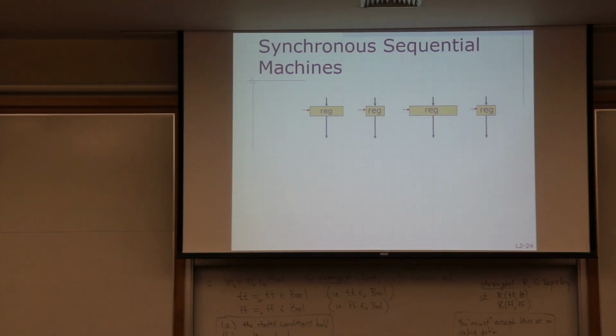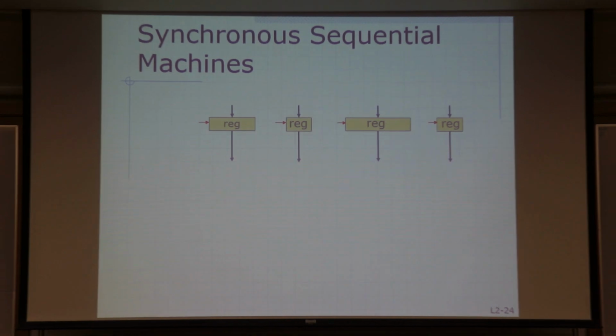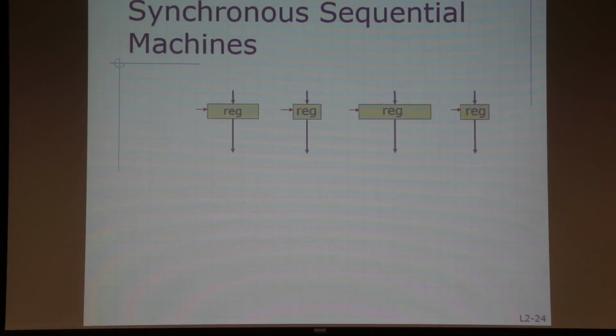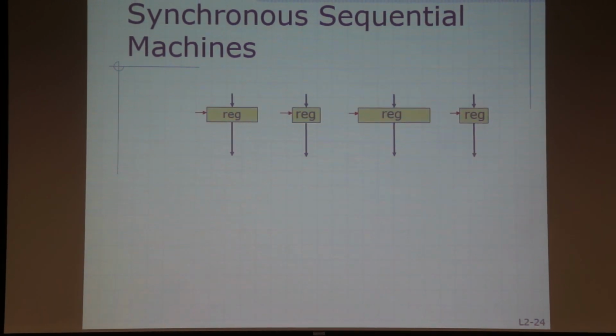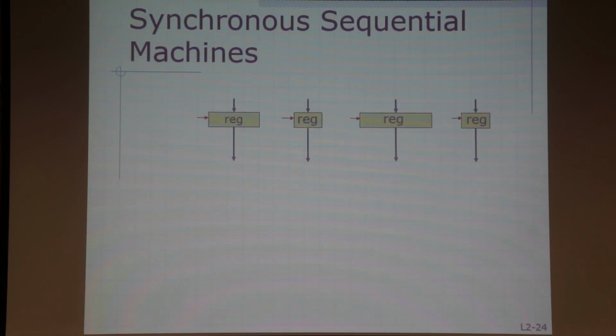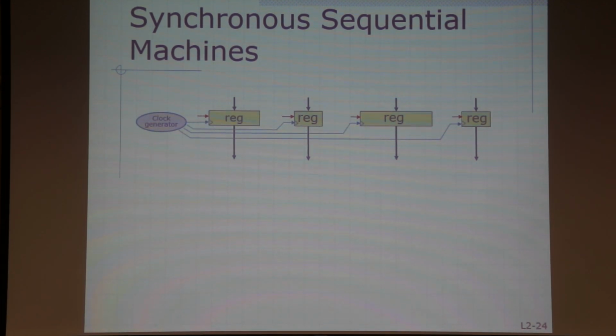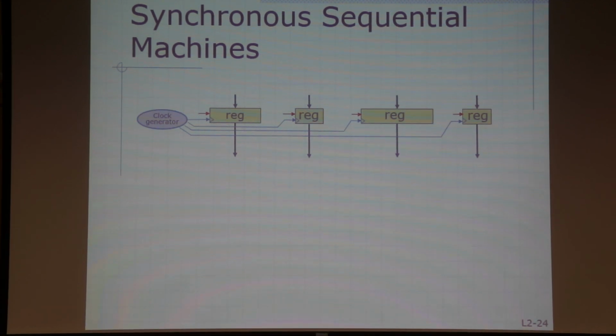Synchronous sequential machines look like this. And the way we are doing it in BSV, we are declaring lots of registers. And registers have enables, that's what those red lines are. For registers, you have to supply some input and you can read the output. So this is roughly the picture for every register you will declare, and its width is completely dependent upon the type declaration you have given it, whether it's 32 bits or 10 bits or 17 bits, up to you. And they all have the same clock. We don't bother with it, it'll just complicate the diagram.